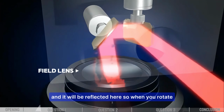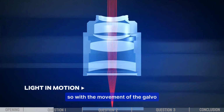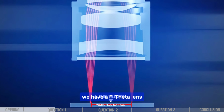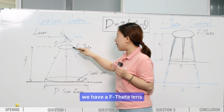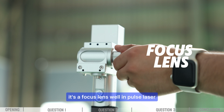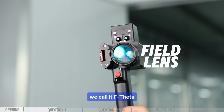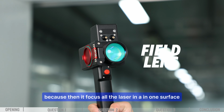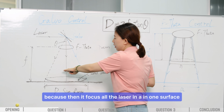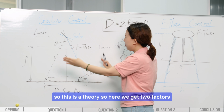So when you rotate, it will go like here. So with the movement of the galvo reflective mirror, after this we have an F-theta lens, which in CW is a focus lens. Well, in pulse laser we call it F-theta because it focuses all the laser on one surface. So this is the theory.